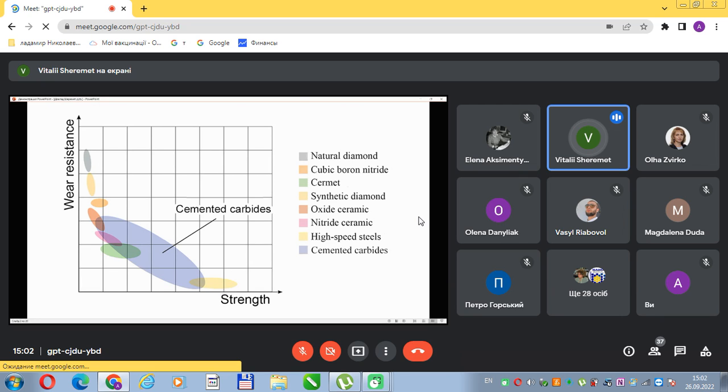The most widely used method of reducing the size of carbide grains is alloying, in fact, doping alloys with grain growth inhibitors. The importance and originality of this study are that it explores the combined effect of preliminary cold isostatic pressing of green bodies and vanadium carbide grain growth inhibitor additive on the average tungsten carbide grain size of sintered bulk.